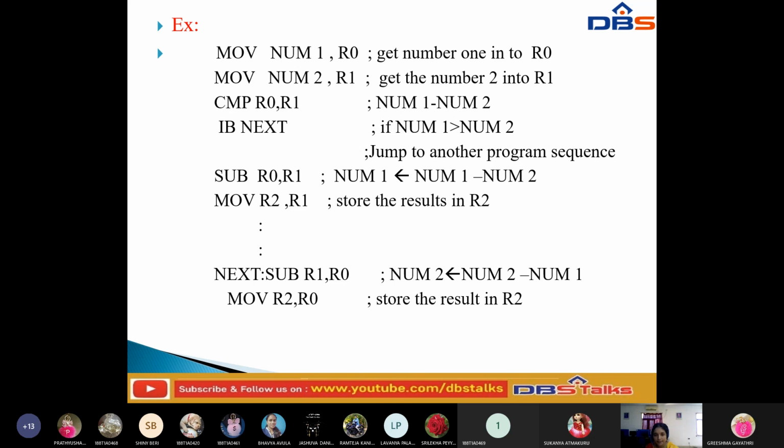Next is the branch instruction. If number 1 is greater than number 2, then it jumps to another program sequence. Okay, so now we have to do the subtraction. I am doing the subtraction between R0 and R1, that is number 1 minus number 2.